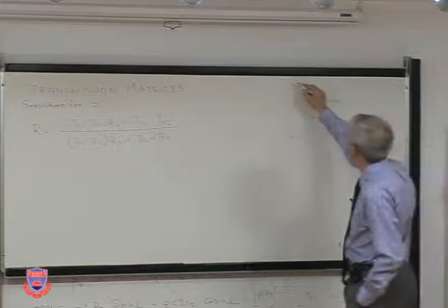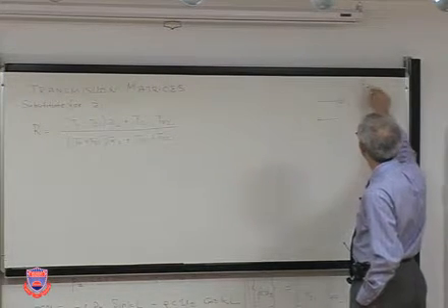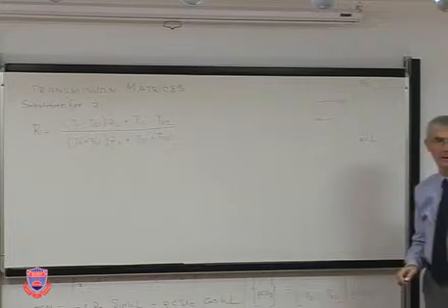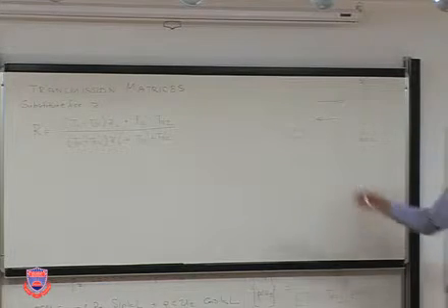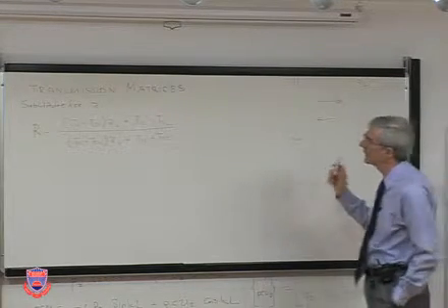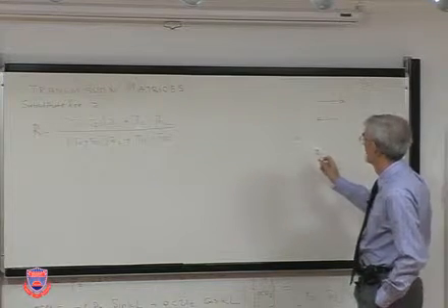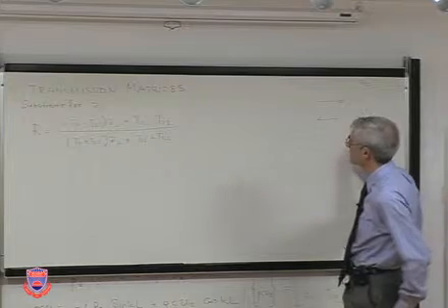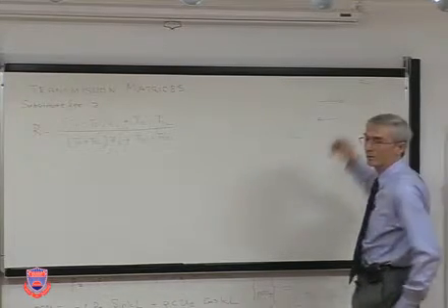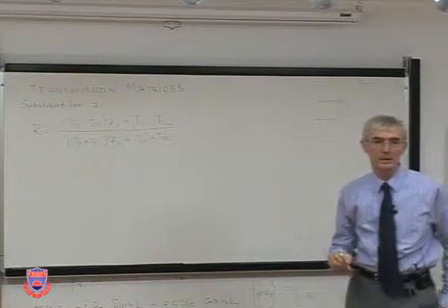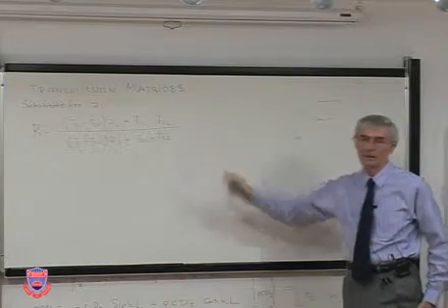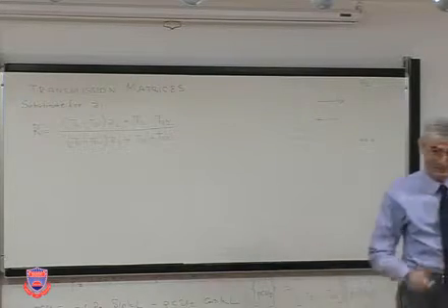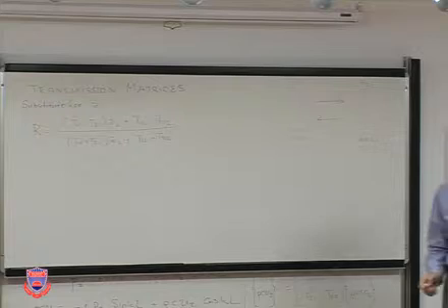And the impedance is expressed as Z1 and Z2 at these spots. What it tells us is, using the transmission matrix between these two spots, and if you know the impedance expression at the other end, you can get the coefficient of reflection, exactly like your problem.